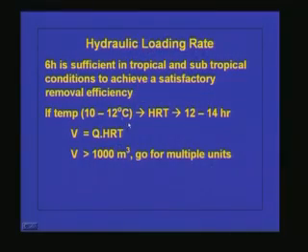In tropical countries the temperature will always be above 25 degrees centigrade. The optimum temperature for the anaerobic process is 35 plus or minus 2 degrees centigrade. So at optimum temperature, the hydraulic retention time required for achieving the desired efficiency is only 6 hours, but if the temperature is less, then we have to provide a high hydraulic retention time.